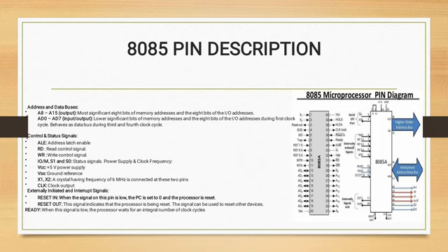Next, AD0 to AD7 are the input and output pins, and here you can see that the address and data are both in multiplexed form on the address and data bus. That means they serve dual purpose. They are used for the LSB, the least significant 8 bits of the memory address or the IO address, during the required clock cycle of a machine cycle.